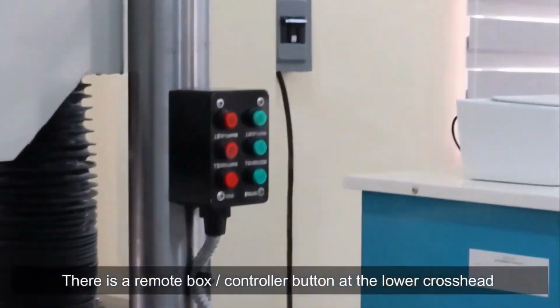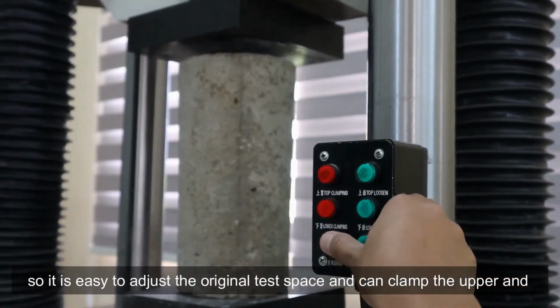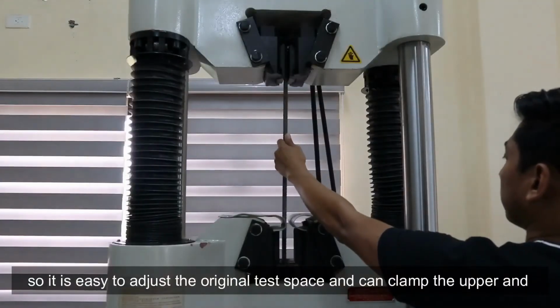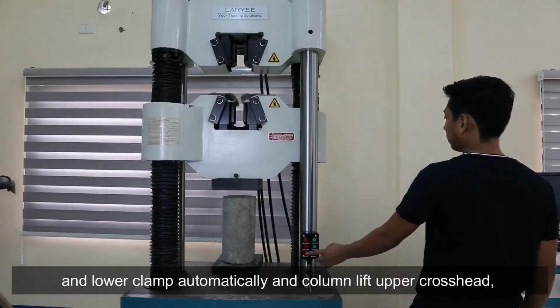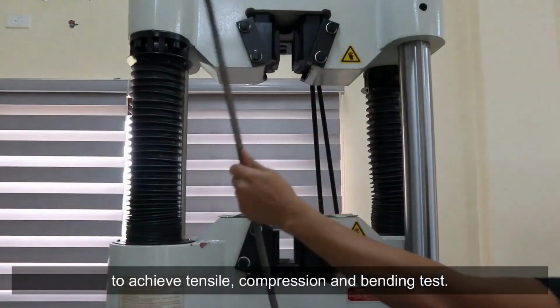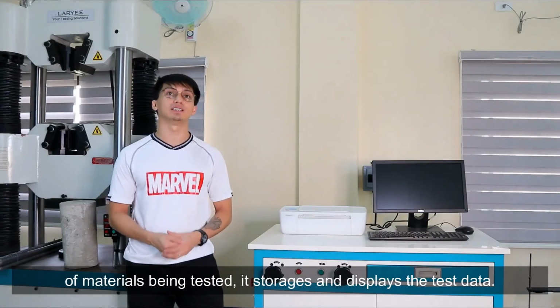There is a remote box or the controller button at the lower crosshead so it is easy to adjust the original test pace and can clamp the upper and lower clamp automatically and column lift upper crosshead to achieve tensile, compression, and bending test. The machine controller is the one that processes the data of materials being tested, storages, and displays the test data.